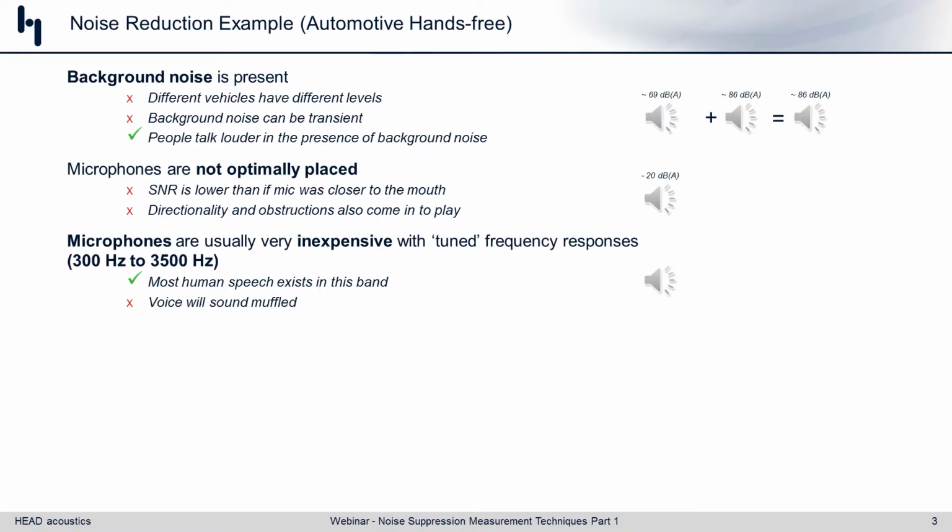The two primary reasons for that, so in this case, roughly around 300 hertz. In a vehicle situation, a lot of the driving noise is actually similar to a pink noise spectrum. So it's very low frequency dominated. There's a lot of energy in the low frequencies in a vehicle from a noise perspective. And if your microphone from just an analog perspective just isn't sensitive to that, great. You have to do less DSP work. You've taken care of a lot of the noise suppression using physics.